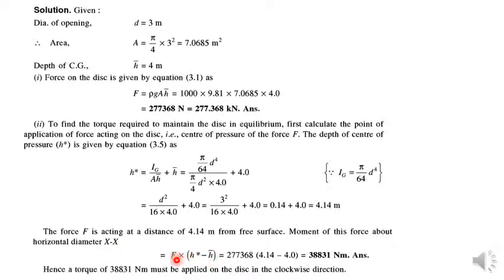Your force is going to be in equilibrium once it produces a moment about the centroidal axis. If we elaborate in a more particular way, we have, around the side of the tank, this condition where we have our circular disc. This is the thickness of the disc, shown over here. This point shows the center of gravity, the G point, and here the hydrostatic force has been applied; this point is represented by P, the center of pressure.